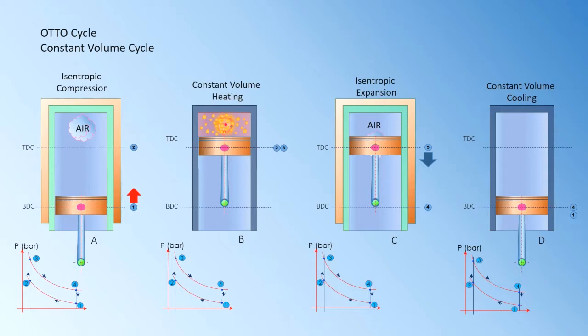So therefore I have 4 cylinders here which I've drawn, and the first and the third diagram is isentropic, so that means it must be perfectly thermally insulated. From the diagrams you can see I have put in 2 fixed positions here. One is called the bottom dead center or the outer dead center. The next one is the top dead center or the inner dead center. So the piston should slide forward and backward within these 2 fixed points.